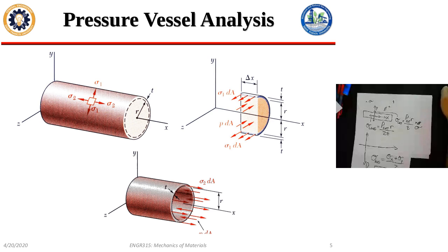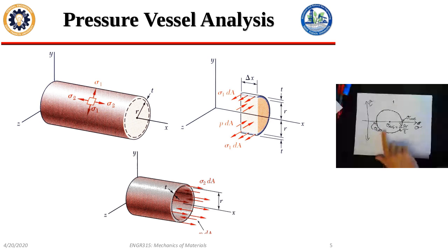So if I look here, I have sigma x, I have a sigma y. You might think I also need a z. We never saw in any of our free body diagrams a sigma z. We didn't see a stress coming into or out of the page. We never saw a force that went into or out of the page. And if there's no force, there's no stress.